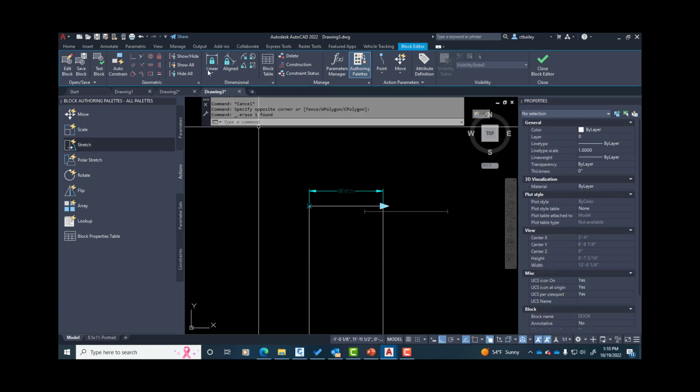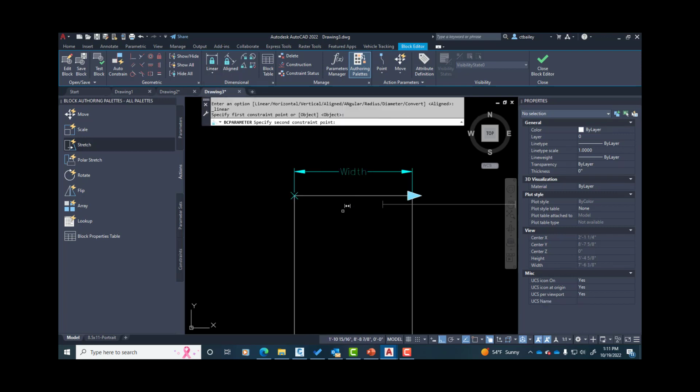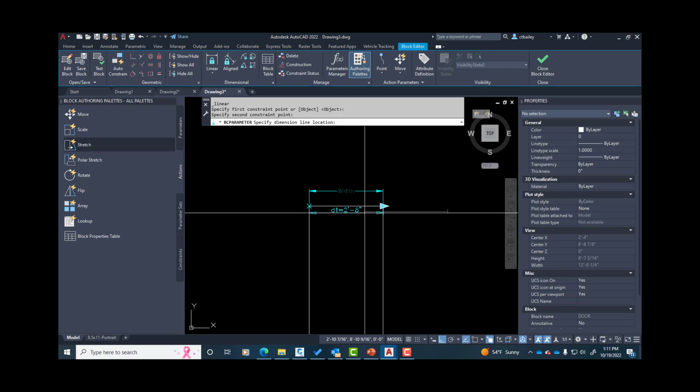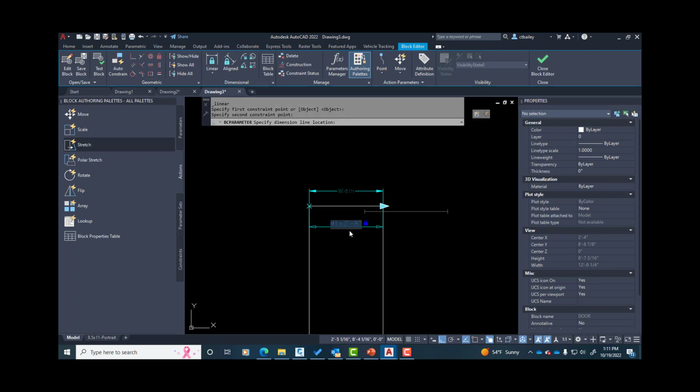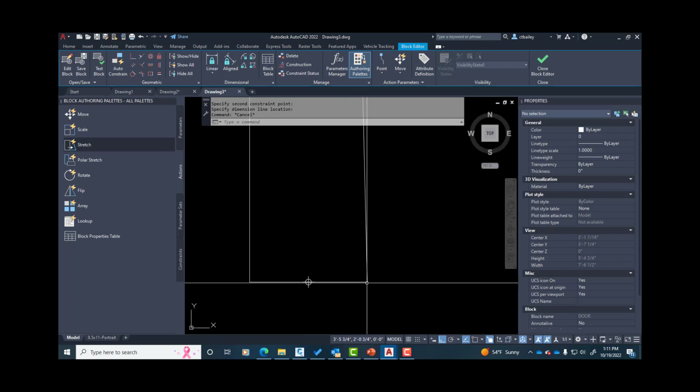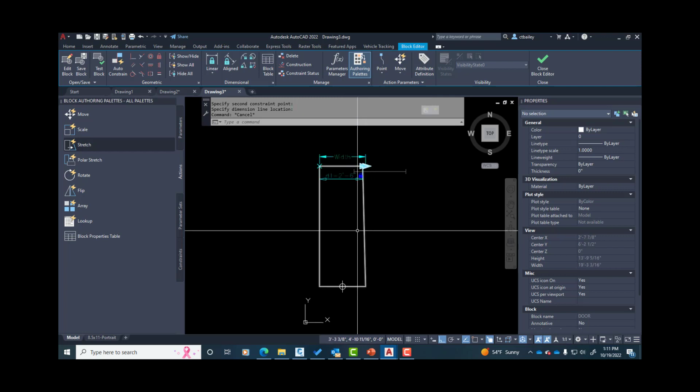Well, remember, we have the linear constraint. And so if we hit the linear constraint and we selected that same top bar, do it again. From that side to that side, put it in here, and set the distance to 30 inches. Type 30. That tugged it in, but notice it didn't hold perpendicular. We can fix that too. Let's go ahead and bring in the perpendicular. I'm sorry, that's the coincident.